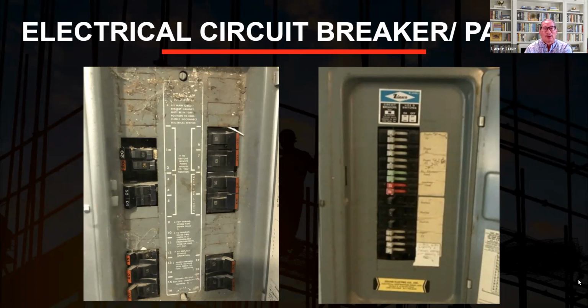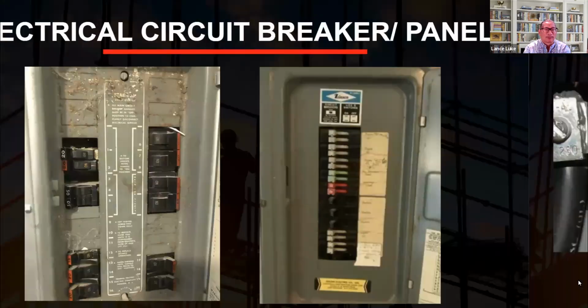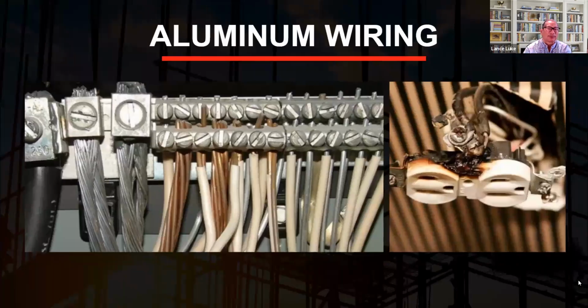Okay, so those two, remember those brands, and it's wise to get an electrician to check it out and see if there's a problem, or just replace the box knowing that that brand is on the list of bad defective materials for electrical. Also, you have aluminum wiring.